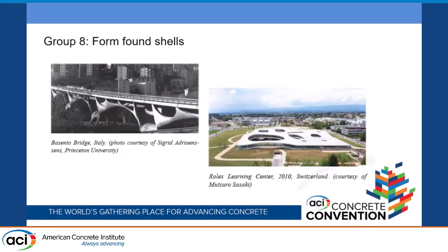And then the neat thing about these type of shells is that once you have these constraints where they need to stop, they can play with the geometry so that the principal stresses inside the shell are all membrane forces. They're all pure axial tension or compression. And so very little bending exists in these shells because of the way they have found the form to just follow those stress lines. And so that's a really cool thing about them.